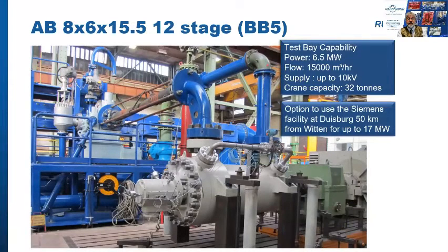For contrast, this is the setup for a normal performance test of a BB5 pump. Note the test pad with slots to allow quick setup and alignment of drive components, test shop pedestals, test shop gearbox on test shop pedestals, temporary seal flush piping, test shop instrumentation.